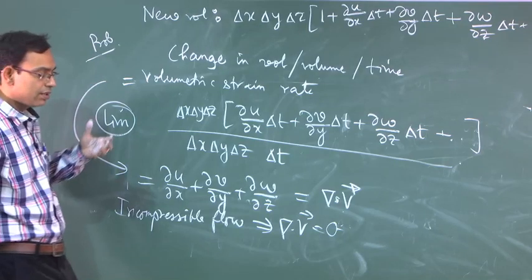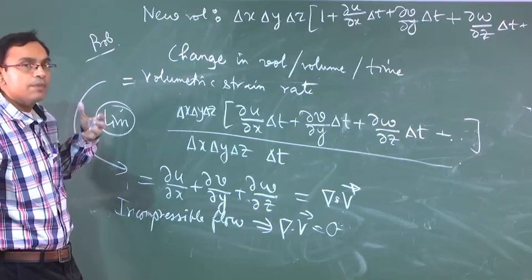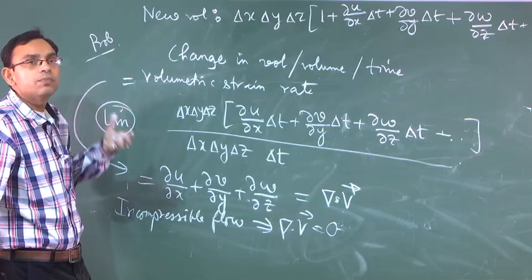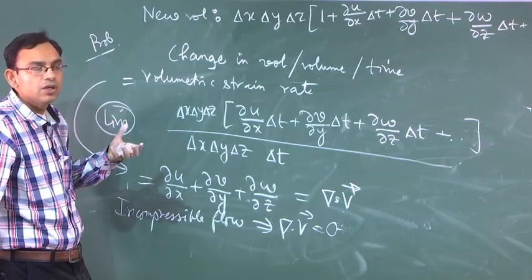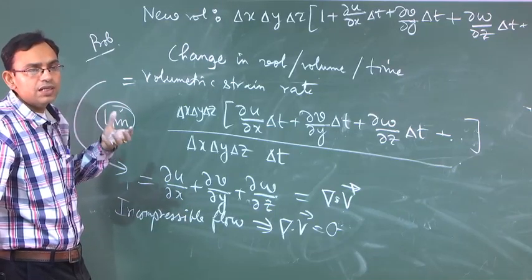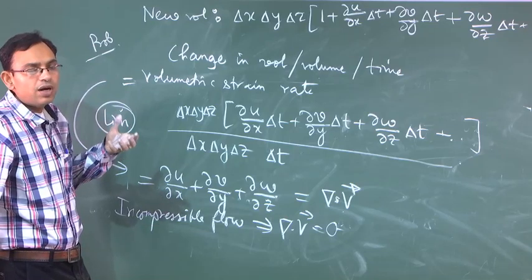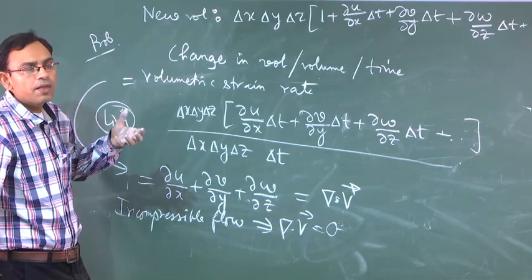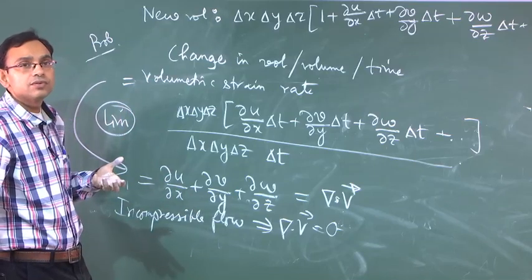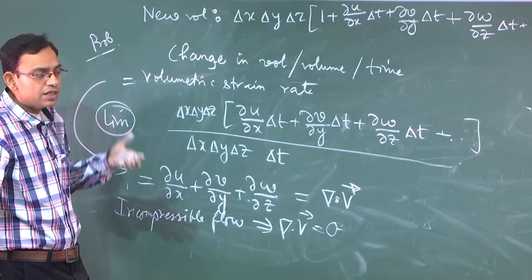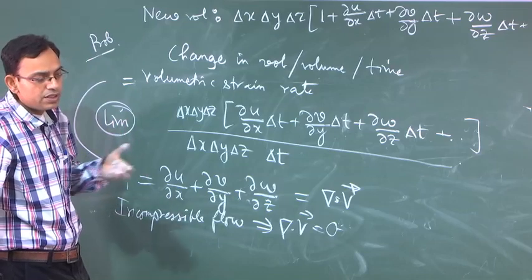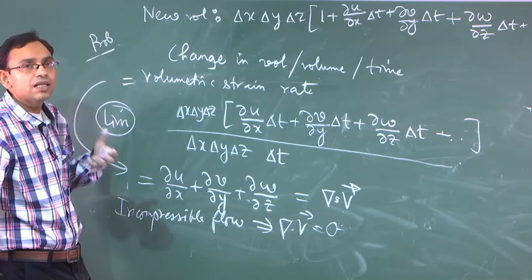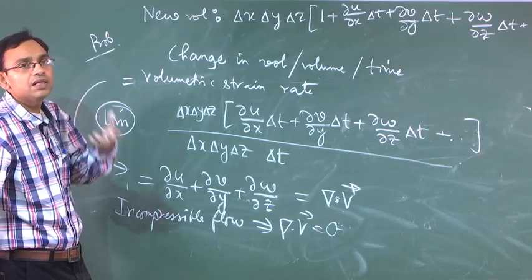For a fluid, as a substance, sometimes we use a terminology called incompressible fluid or compressible fluid. Then what we essentially mean is the strength of dependence of density on pressure. If the density is strongly sensitive to change in pressure, then of course we say that the compressibility effect is there in the fluid.